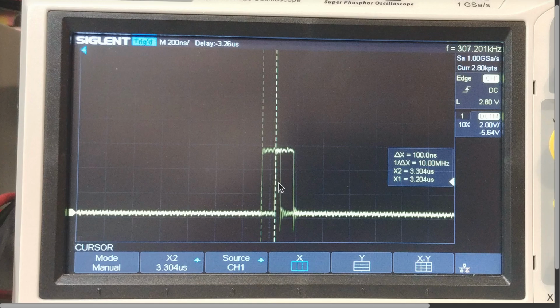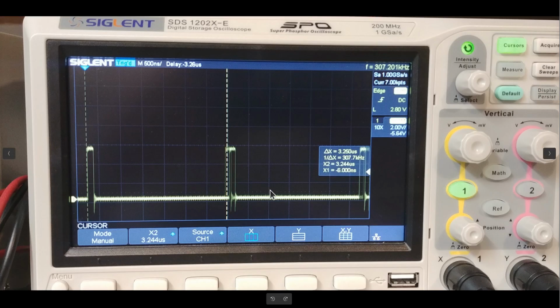The other thing that you want to be aware of when you look at this on a scope is the fact that the CTC doesn't generate a wave that's got a 50-50 duty cycle. If you're not really thinking about what's going on here, you might think this goes up for 50% of the time, down for 50% of the time, up for 50%, and so on. No, that's not how it works. Remember, the zero count timeout signal is true when the timer equals 0, and then it slams back down here, okay? So it's 0 here, and it's not 0 all the other times when it's counting. It goes up when it's 0, it goes down when it's counting, and so on.